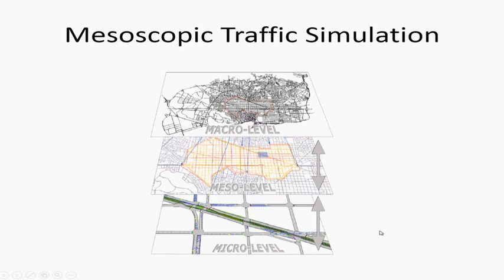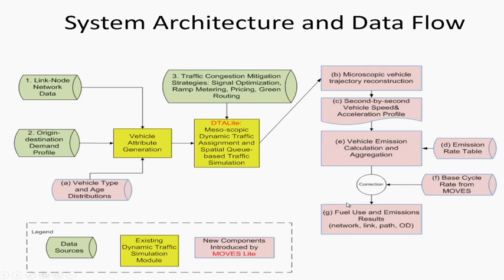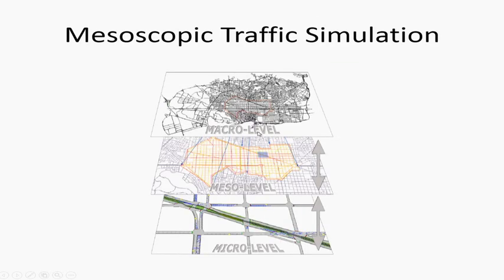Before I move into the DTA package, I would like to introduce the 3 layers of large-scale, region-scale, and also intersection-level simulation, if you want to call that. So we have the macroscopic simulation, typically a static traffic assignment. A mesoscopic simulation, where we simulate the traffic agent by agent. And also we have this car-following type micro-level simulation. The typical packages could be VISSIM, could be Paramics.